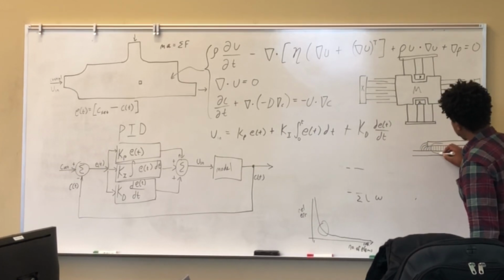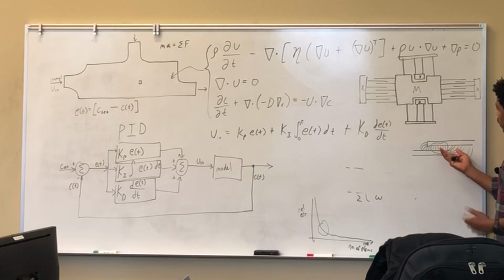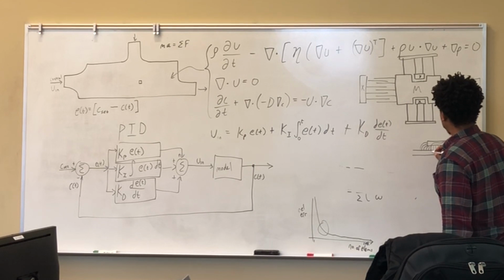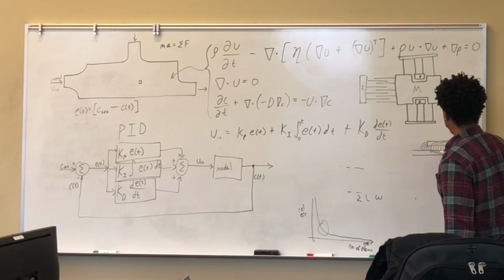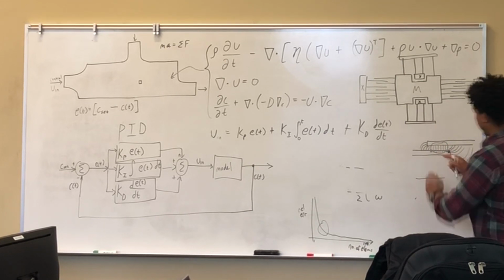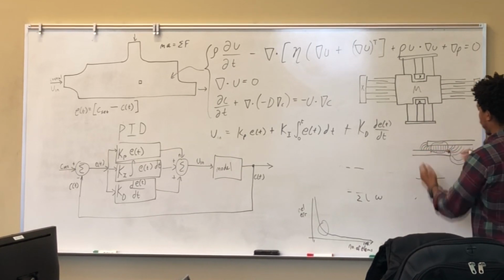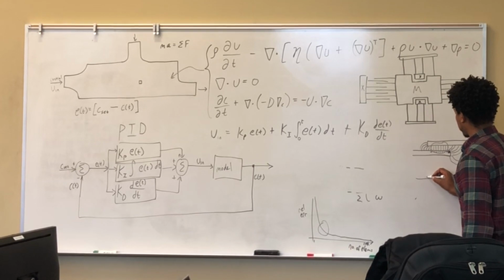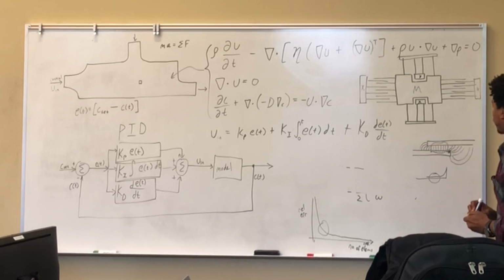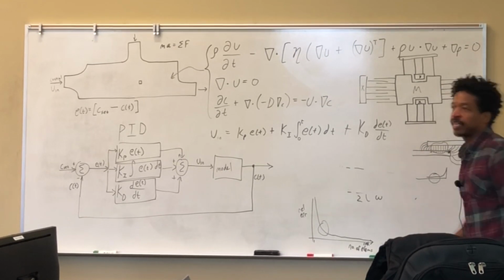So in here is like a parallel plate capacitor, and we can determine what that is even analytically by hand. But out here it gets a little more complex where these fields are fringing. And what we'll find out is that the concentration of charge is quite constant along here, and then it bunches up on the ends right here. Okay, and we'll be able to plot along this surface the charge density. If you were to take this edge right here and plot the charge density, it'll look sort of like this. When it comes to the edge, it'll peak up like that at this point in the edge right there. But here it looks like just a simple parallel plate capacitor model. But that's it for Thursday.